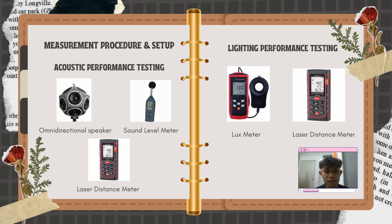Next, we take readings. We measure the light at each spot, making sure nothing blocked the meter. Next, we write it down. We record the light meter, the light level, the time, the light type, and any issues like glare. Lastly, we check with the standards. We compare our readings to the recommended light levels, which is 300 to 500 lux, to see if changes are needed in the room.